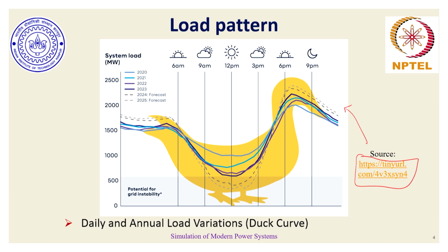Depending on how we live our lives, typically normal human beings get up in the morning and hence the electrical load requirement goes up because of heating load, lighting load, electrical appliances usage and so on. After getting ready, we go to our schools or offices, which is where we spend our time traveling, and as a result the typical electrical load tends to go down. And once we are back to our homes in the evening when the sun goes down, the electrical lighting load requirement goes up, and hence in the evening hours again we do have a peak.